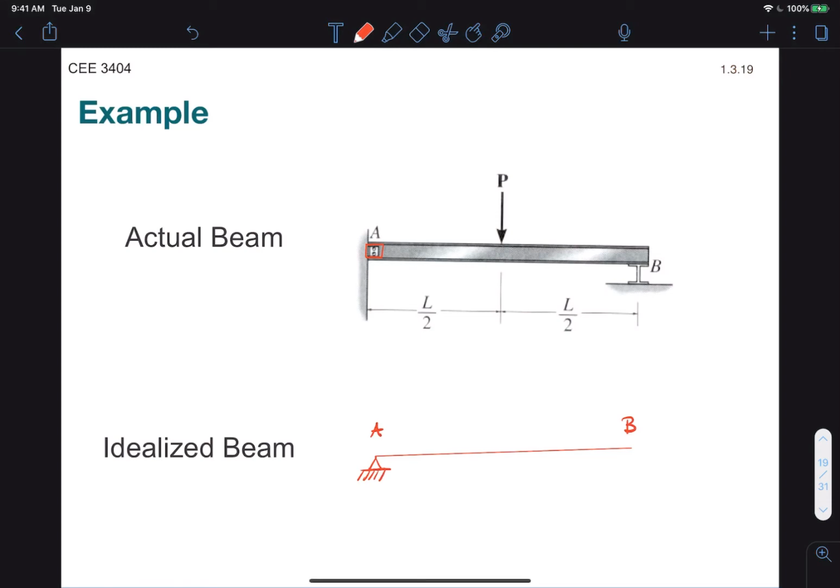And on the other side in B, this is essentially lying flat on a support member. Okay, so that basically does not limit anything other than vertical motion, right? So I assume that the beam is free to rotate around that point, kind of like a rocker. So that's going to be, for me, a clear sign that that is a roller, right? And I put the load in the same place. And so my reactions will be AY, AX, and BY.